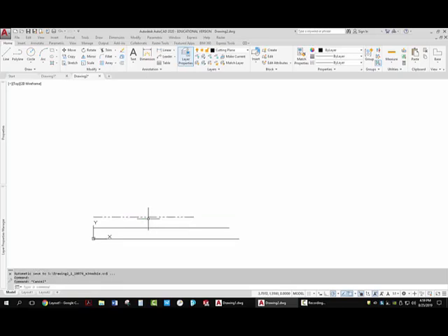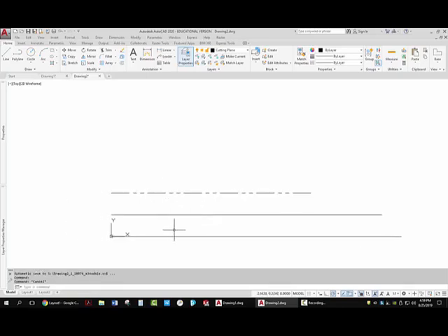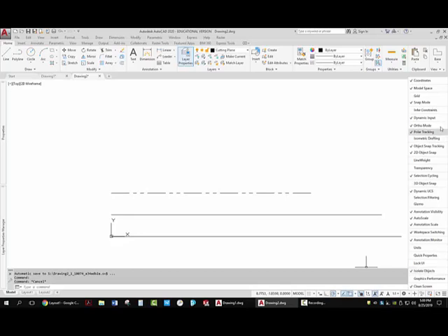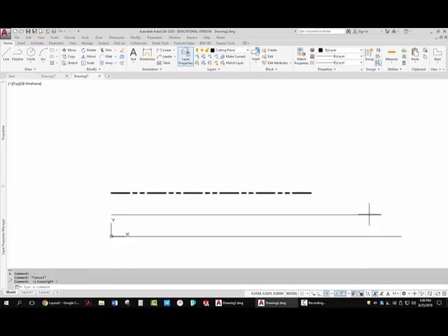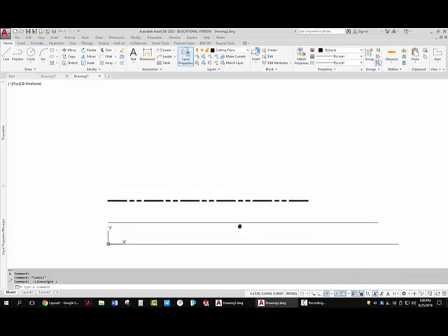It's a little shorter line, and you'll notice it automatically drew a different line type. Now it automatically drew a different line type, but it didn't show me the line weight, even though there was a line weight assigned. To do that, I need to go back over to the status bar, over to customization, and I need to turn on the line weight button, and then I need to come down and use that line weight button to turn on line weights. And you'll notice now that I've done that, I can see the line weight. Highly recommend you have that button showing down here. It gets a little bit confusing sometimes. At least it gets a little cluttery, so some people like to just turn it on and off. I'm going to leave it on for right now.